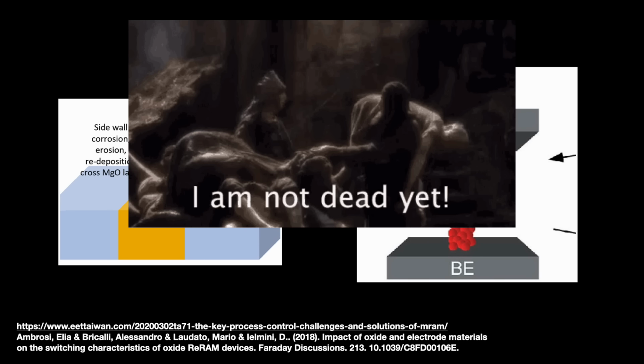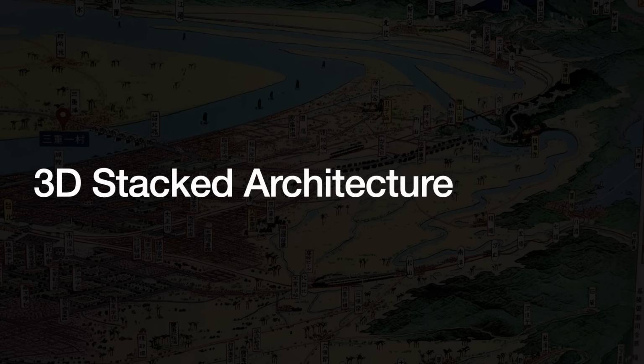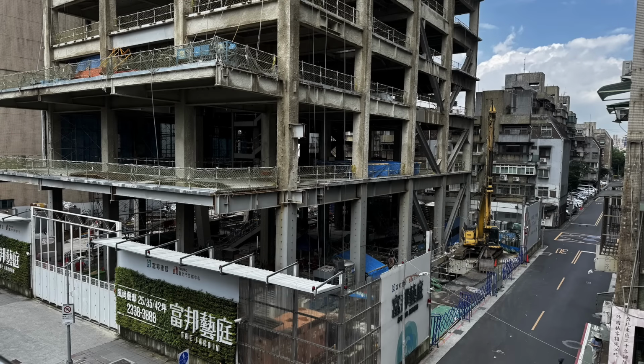If we can't grow bit density by shrinking the cells, then let's grow it by stacking more cells on top of each other. The first attempts at 3D NAND simply fabricated layers of 2D memory cells on top of each other and connected them. Each NAND layer is its own self-contained array. Imagine as if you were building a multi-story Asian mall, you completely finished each floor of the mall before moving on up to the next.